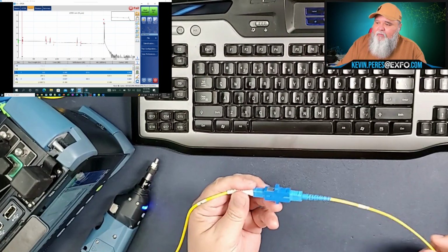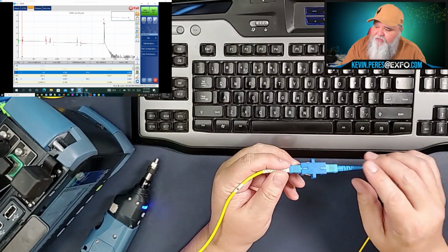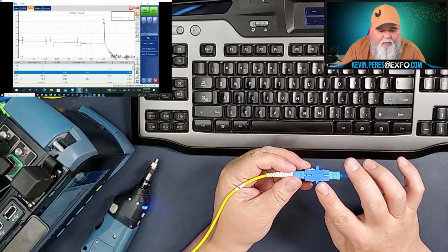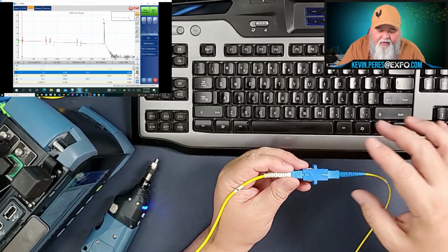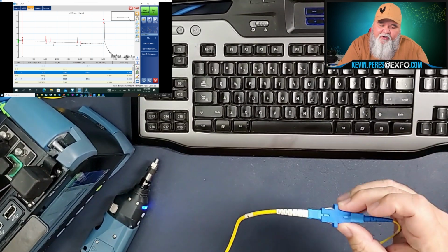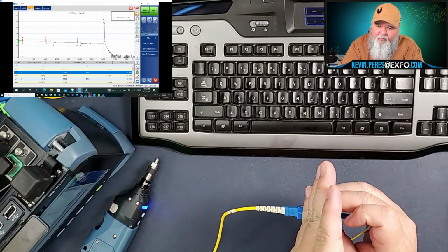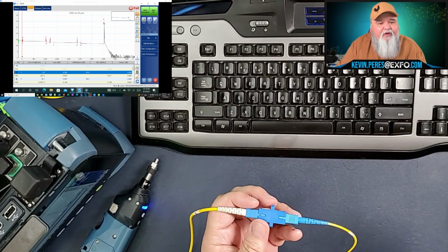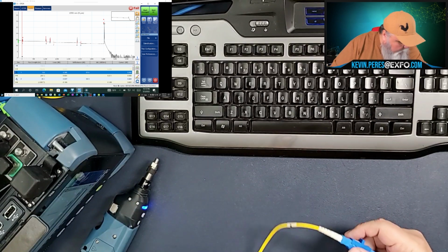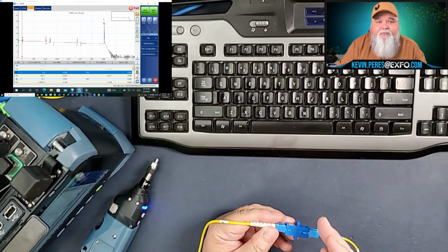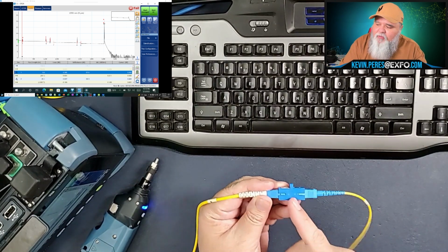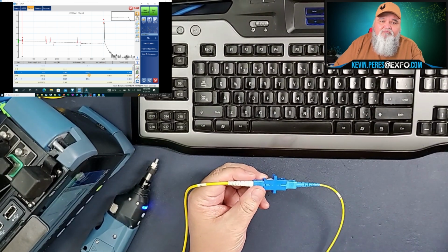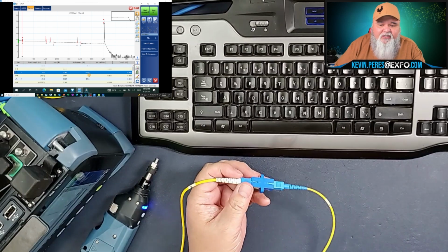And so this is what I'm looking at right here, right? So I have the OTDR tray still up. So this right here is 150 meters away from my OTDR port. This is essentially, in this demonstration, my FTP panel. You know, my first panel, could be tie cable panel, whatever. And then 20 meters away, I have somewhere an APC connection. Right, but I want to troubleshoot this one because it's right here in my hands. This is that neg 57.8. Well, heck, that's a good reflection. I don't have to worry about it.